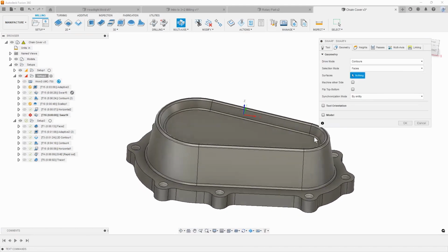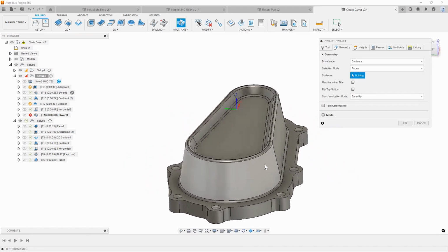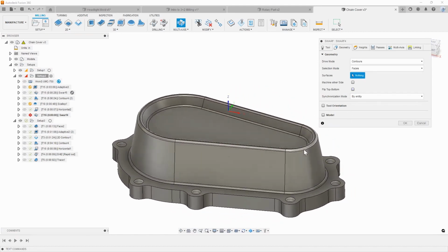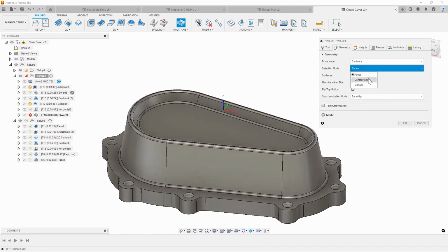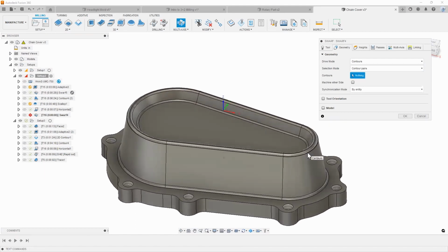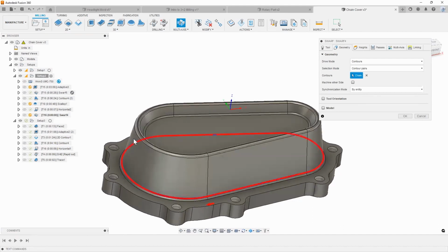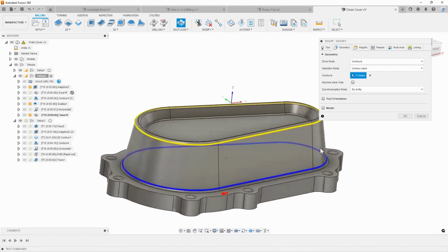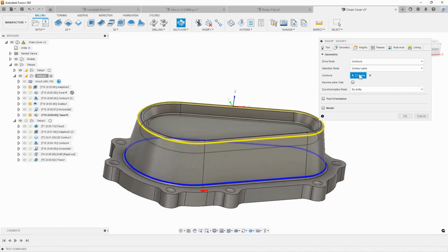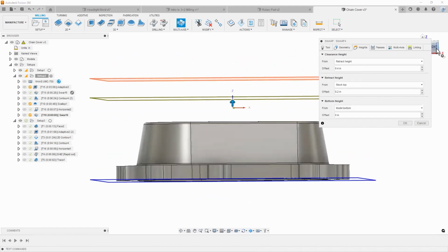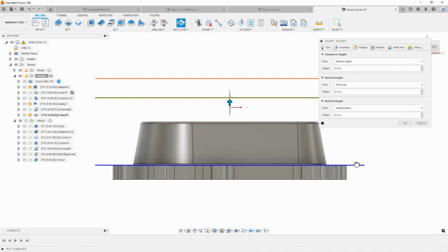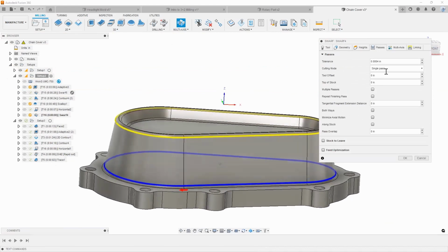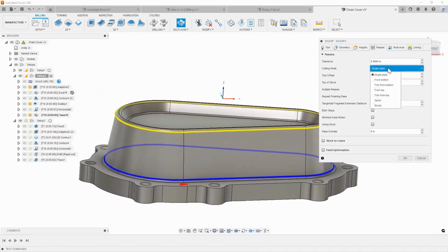And then typically we can either drive our toolpath with faces or contour chains. So what I'm going to do here is pick contour pairs or do a manual. Then all I need to do is give it a chain that I want to follow. The next step is to give it a driving chain that keeps the tool center on that location. Then I can also decide where my heights want to be. So I'm going to increase this up so that I don't cut past that point right there. You can also decide if you want to do this in a single pass or multiple passes.